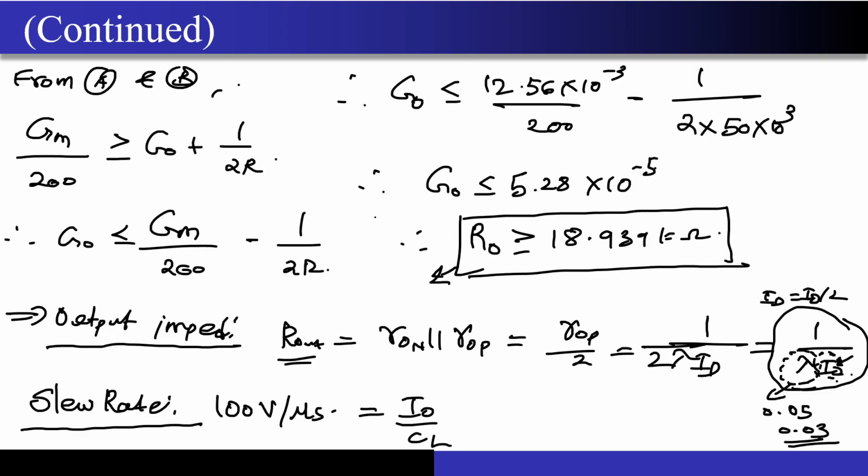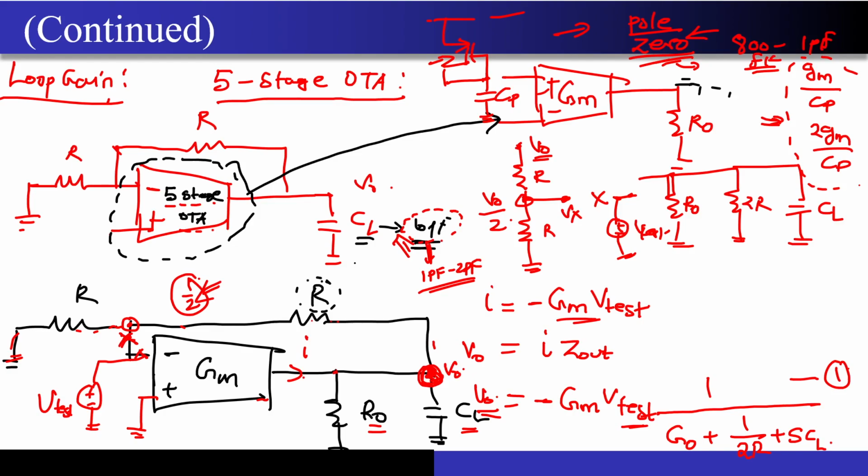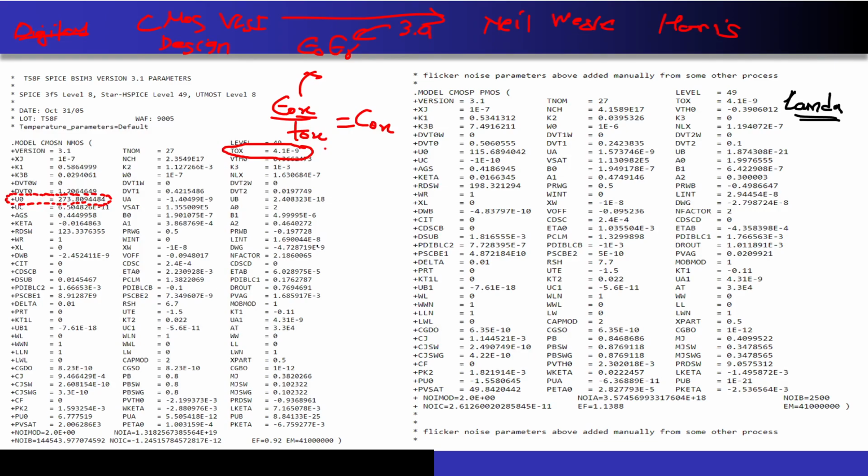And remember, even though we have ignored the parasitics inside this particular transistor, if the output capacitance was smaller, you would have been forced to include the poles and zeros that were present within the 5-stage OTA itself. Now to make your life hell, remember what these parameters are. You guys remember when we talked about the capacitances in the MOSFET? I had discussed the junction capacitance, the sidewall capacitance. You remember this, right?